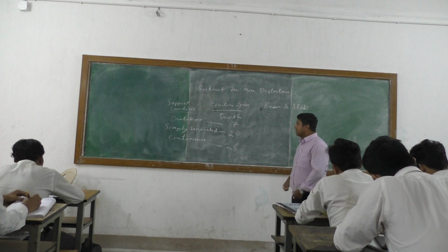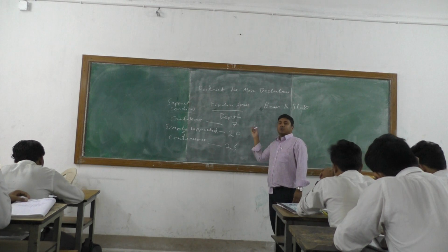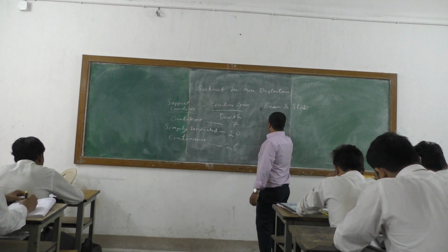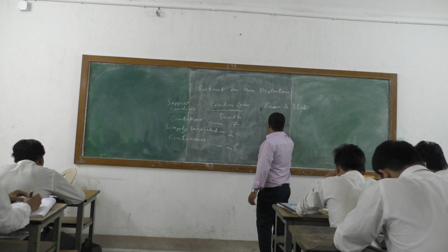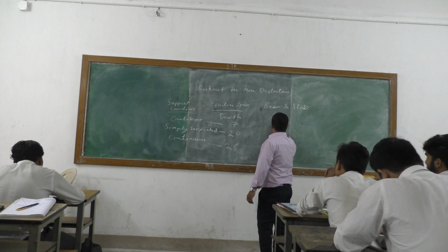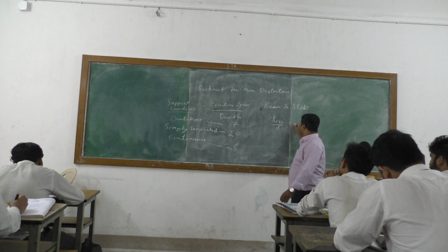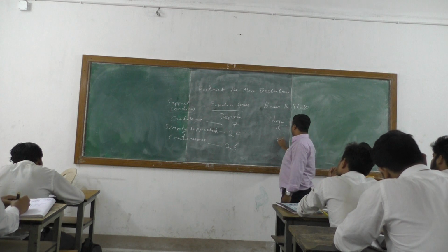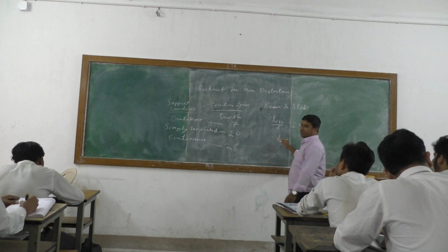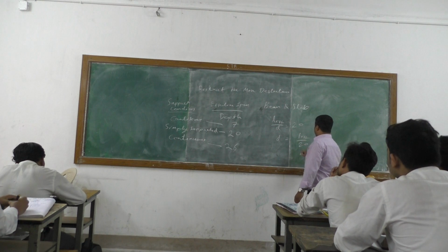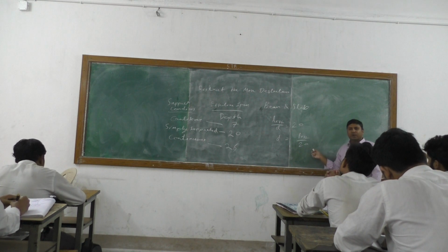So it means that we can get this effective length, suppose L effective by D for any simply supported beam, given as 20. From here we can get the limiting depth by dividing by the factor 20.